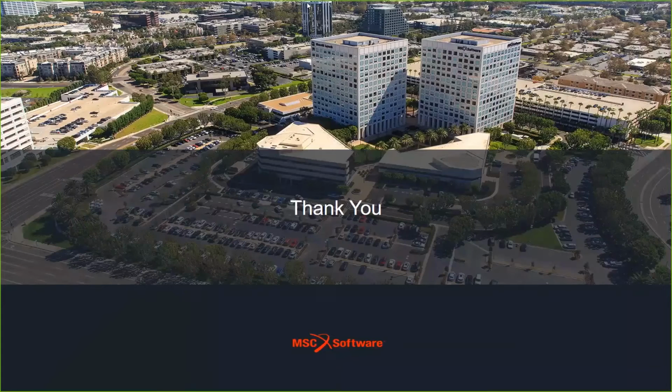Okay. There are a couple of questions on the soft soil tire model. I know we didn't go into it in a lot of detail, but can you elaborate on things like use cases? The soft soil tire model in Adams Tire is a rather basic model. It's based upon the Bekker and Wong technology. It can deal with the kind of roads that you already have in Adams, in the same format.